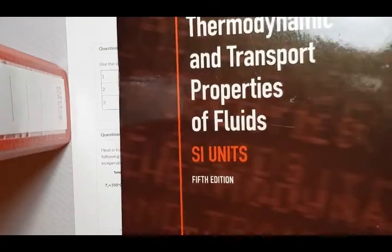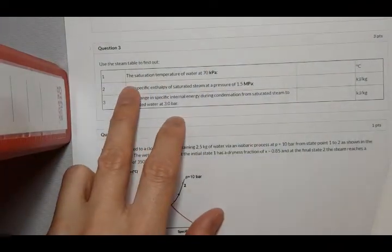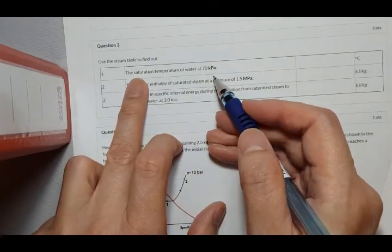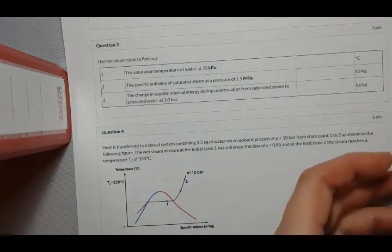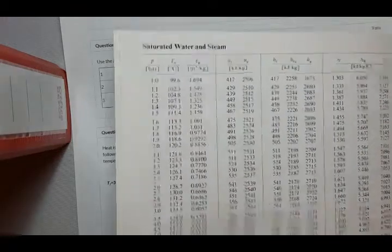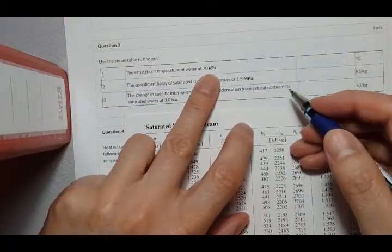Also, I have uploaded a PDF version on Canvas, so you have to use this version. So now we're going to use a steam table to find all these values. The first one, the saturation temperature of water at 70 kilopascal. If you have a look at the steam table, all these pressures are in the unit of bar, so you have to convert kilopascal to bar.